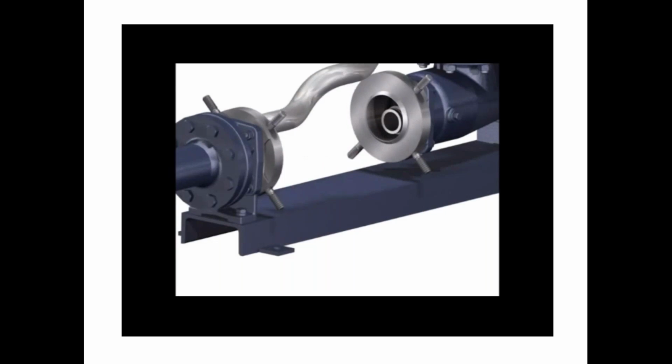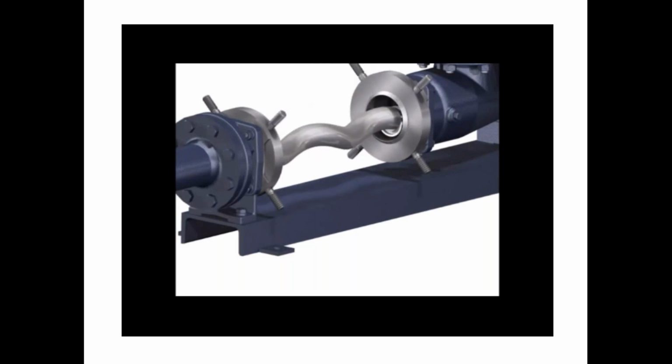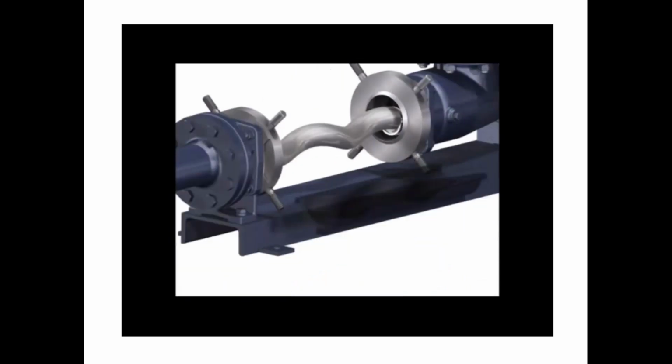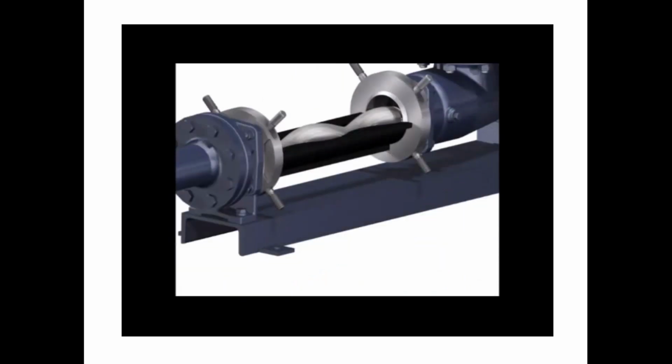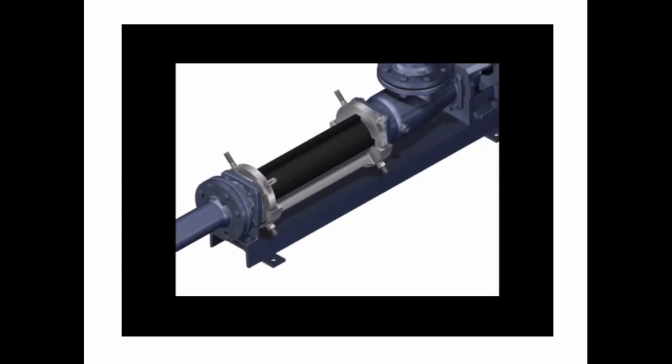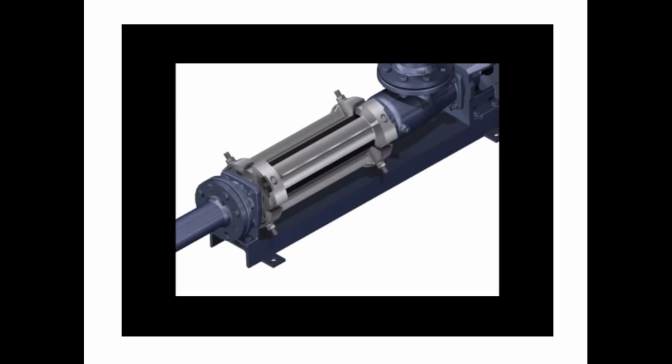So not only was this pump able to be maintained and repaired in place without touching any piping, but this pump was also adjustable so that the end user can get longer life out of the spare parts and the wear items on the pump. This right now is simulating the pump being rebuilt with 2 pieces of rubber, which are the stator, the metal adjustment plates, which are always reused, and a new rotor, which was put in the plug and play design.